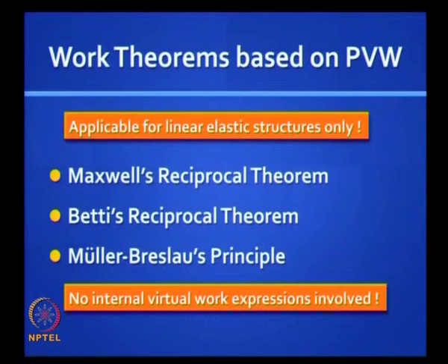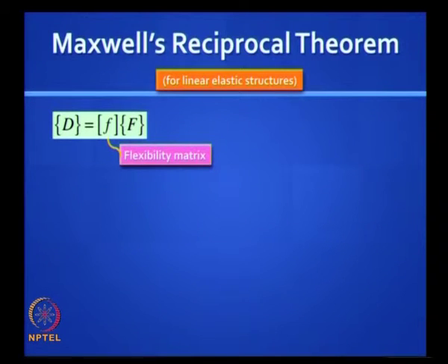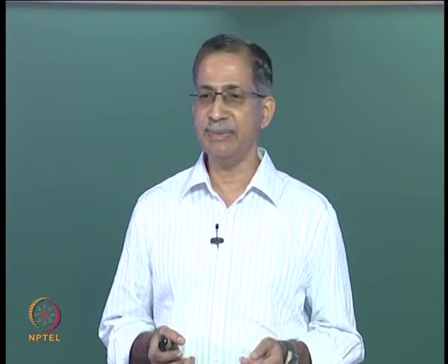The important point to note is that these theorems are applicable only for linear elastic structures, and unlike the principle of virtual work, which requires you to compute both external virtual work and internal virtual work, here we skip the calculation of internal virtual work altogether. So Maxwell's reciprocal theorem in its modern form basically establishes that the flexibility matrix is always symmetric.